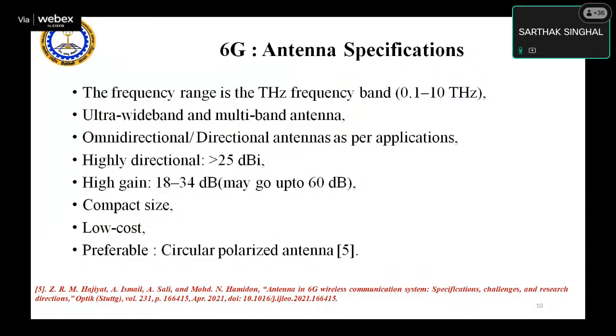Now when we are talking about a multiband antenna, in case of this multiband antenna, you can achieve a higher gain and a slightly longer range of communication in comparison to the ultra wideband, because the ultra wideband is covering a wide range of frequencies, so the gain will be lesser. So your range of communication will also be lesser.